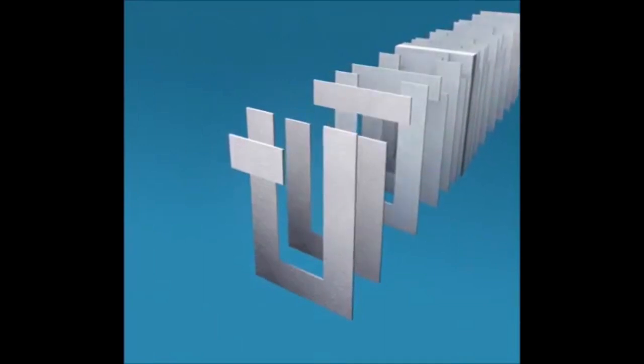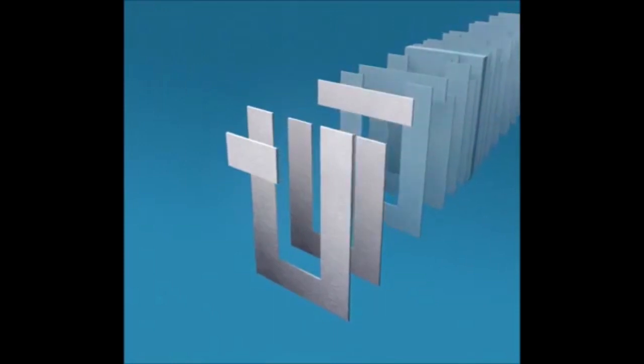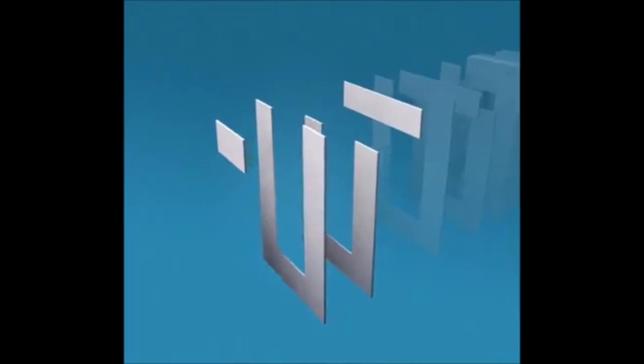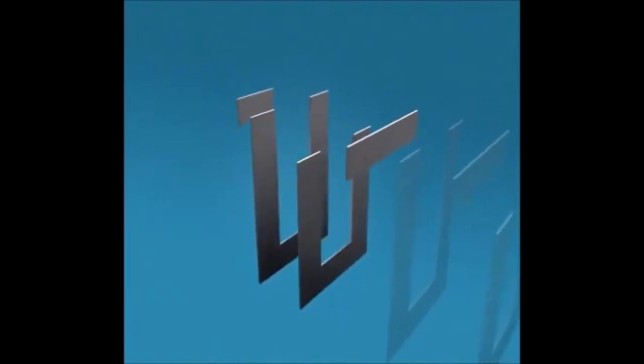The core is used to provide a low reluctance path to the magnetic flux, but the core is subjected to circulating electric currents. These circulating currents, called eddy currents, produce heating and energy losses within the core, resulting in a decrease in the transformer's efficiency.